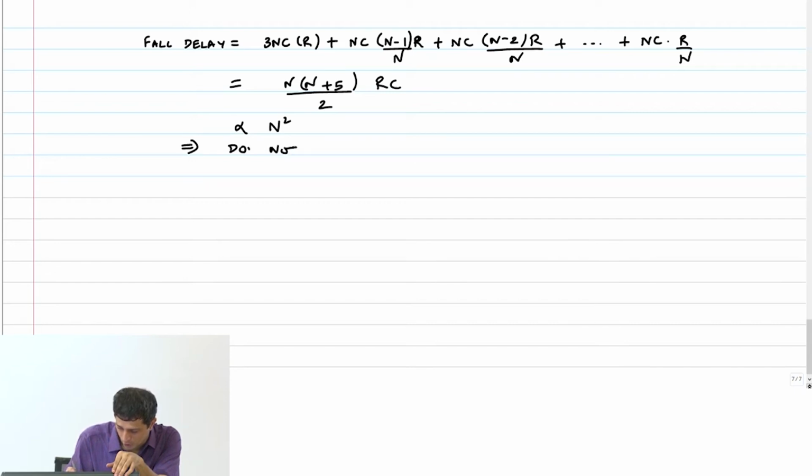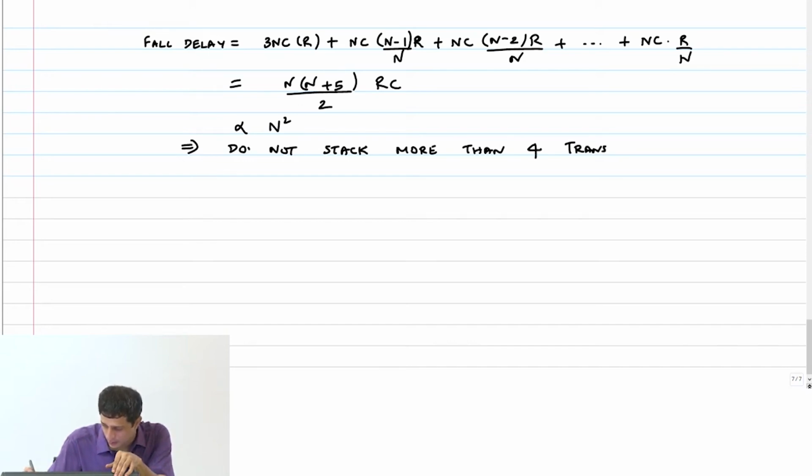So the key conclusion here is, do not stack more than 4 transistors in general, PMOS or NMOS.